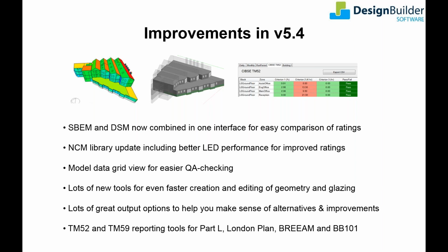Many of our customers are now doing MES work for their clients, and they've found that whilst DSM generally provides a better rating due to more accurate and detailed calculations, that isn't actually always the case. Occasionally, the simplifications of the SBEM engine result in a better rating. So DesignBuilder's unique ability to quickly check this has been really well received by those of you out there doing the MES type work.